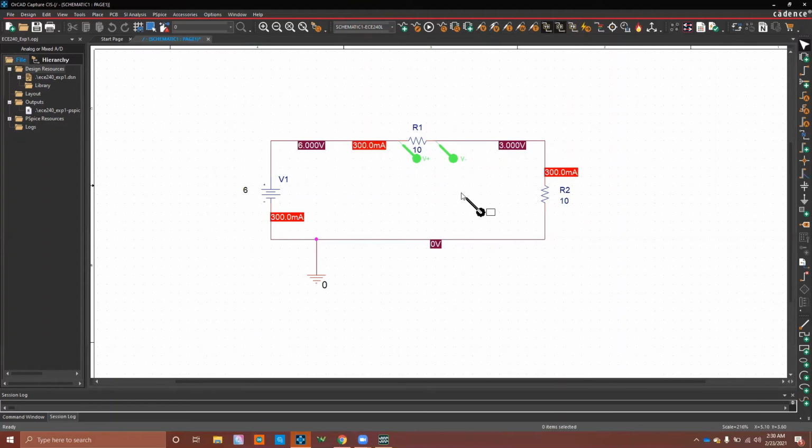Similarly, when we have a circuit element placed vertically, like this resistor, we would then go top to bottom, like so. Okay, so what these probes would be doing is showing a waveform of the voltage across the resistors. And it's going to be voltage because the probe that I chose was the voltage differential marker.